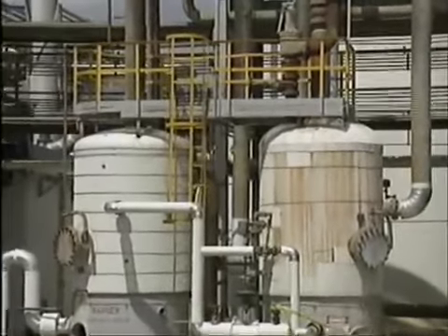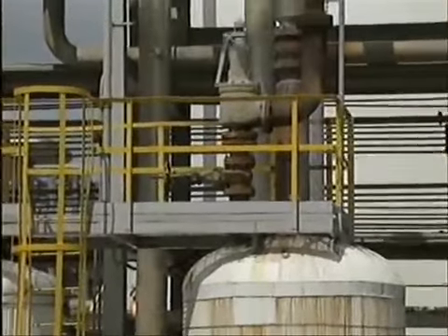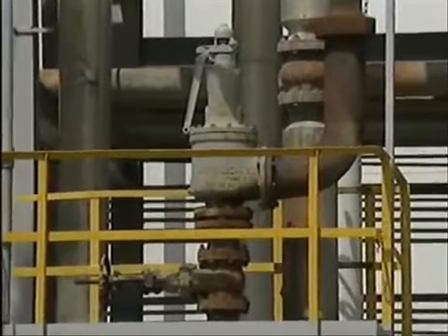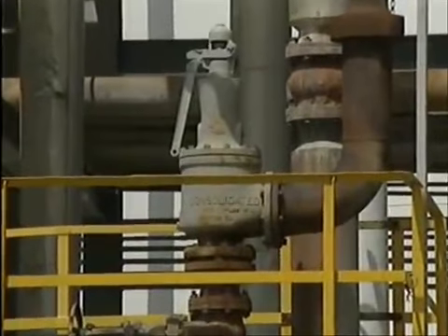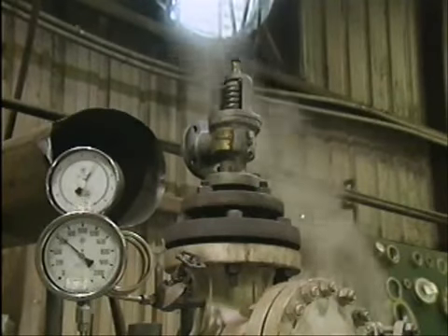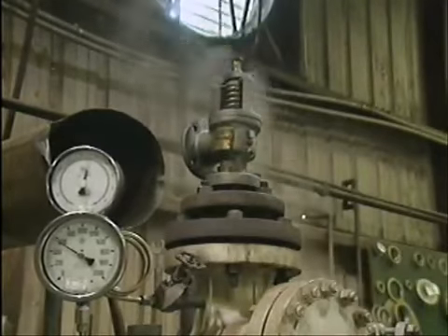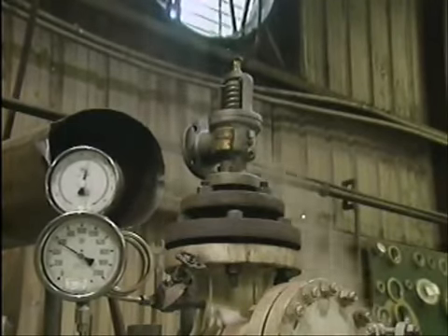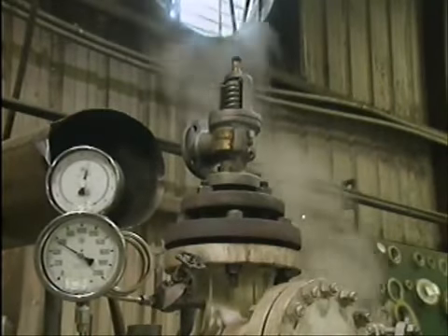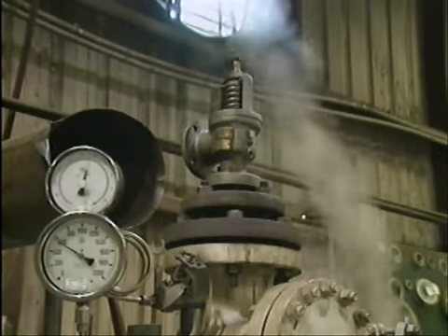Safety valves are commonly used on gas or steam lines because the volume of the gas or steam increases as pressure decreases, and a gas that's under pressure may expand to a tremendous volume when the pressure is relieved. One thing all safety valves have in common is that they open wide very quickly and stay open until the system pressure drops a predetermined amount below the point at which the valve is set to open. The valve allows a large volume of gas to escape as pressure is reduced.